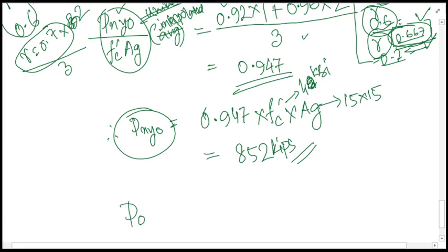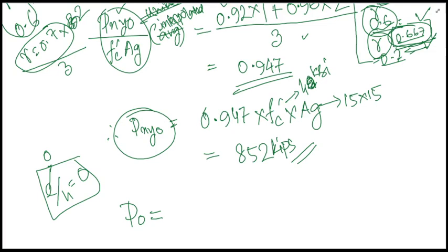And also you can calculate the nominal strength for a concentric column. When it is a concentric column, e by h is equal to 0, as there is no eccentricity. So e by h equals 0 in both of these two graphs, whether gamma is 0.6 or 0.7, is this line itself.